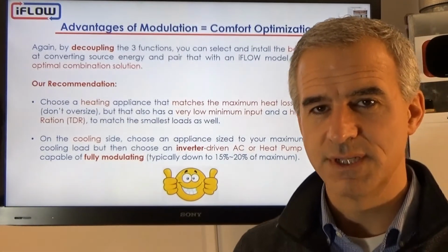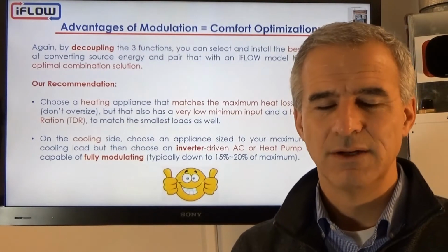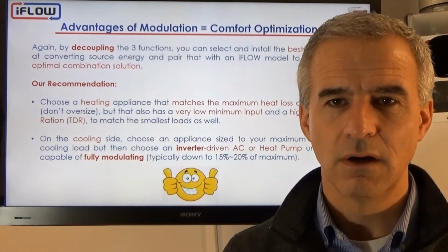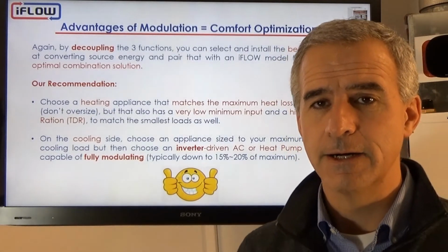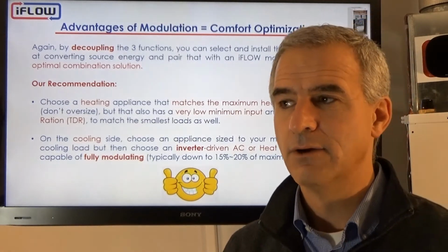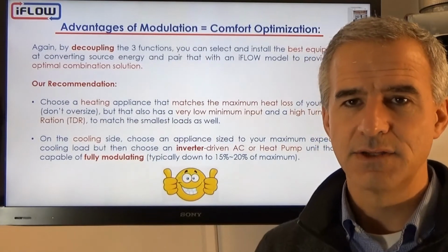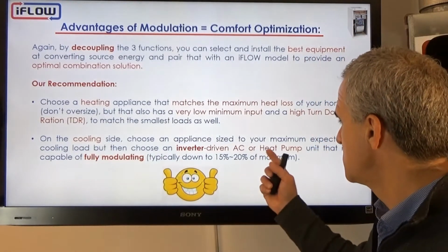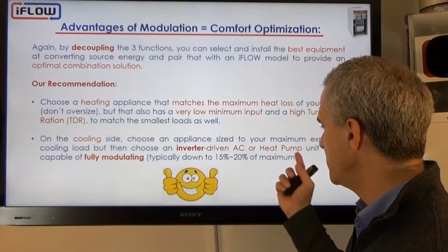And then before it freezes up, it goes into defrost mode. So then you're in defrost mode. What it means is your equipment's running longer than it needs to. So really there's going to be additional cost if your equipment is oversized. So it's not going to function properly, or optimally, let's say. It's not going to run optimally, and it's going to cost you more. So there is an incentive to go with an inverter driven system.